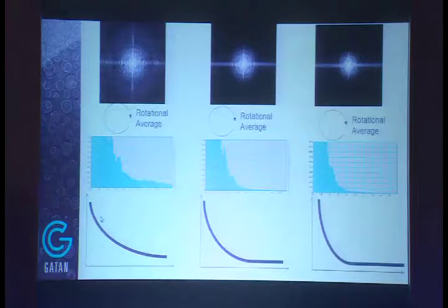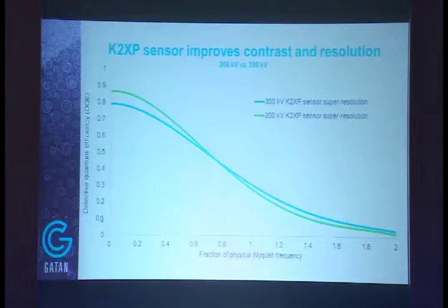Now, I'm not going to say very much about DQE, but I did want to show this one curve highlighting the DQE of our cameras. So DQE is our signal-to-noise ratio as a function of spatial frequency, okay? And what I want to highlight here is that we have very strong signal-to-noise ratio for low-frequency components, and it falls off as we get to higher frequency components, okay?